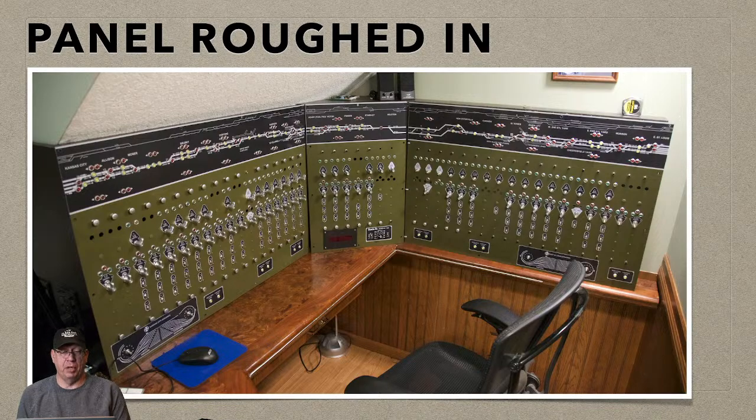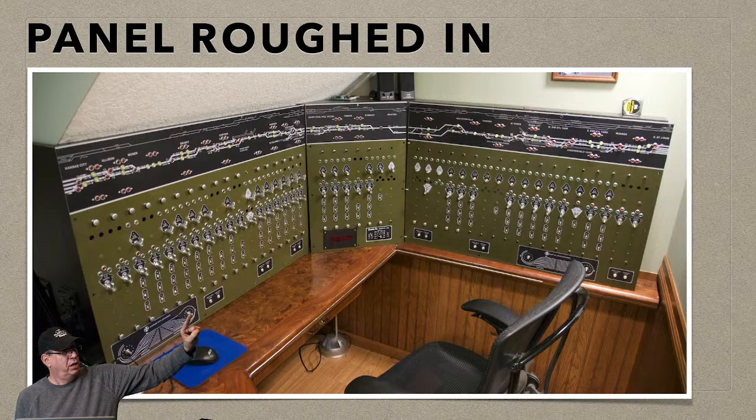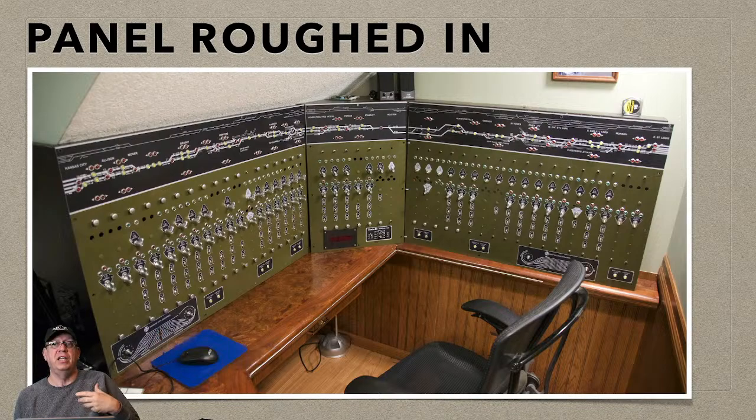You'll notice down below along the bottom here, we've got all the controls for the staging yards. This is the staging controls. There's a rotary switch right here and on the other end right here that are used to line the switches in through a diode matrix into the tracks. And we also have occupancy lights that'll be on this, as well as lights that will show what track is lined into the staging yards on each end of the railroad.